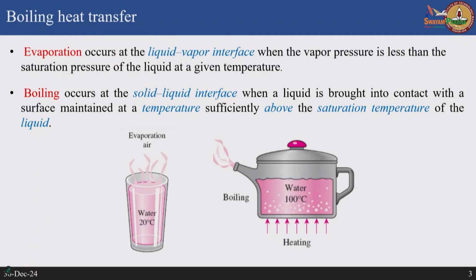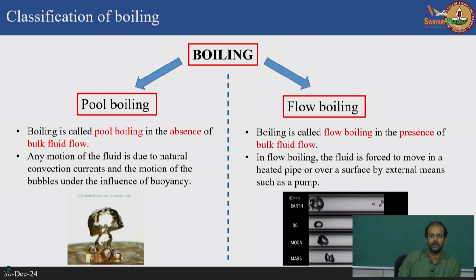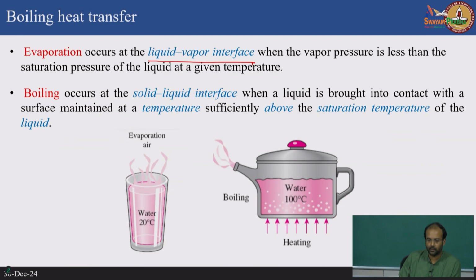Anyway, another important thing when we talk about boiling is you have to understand, technically as a heat transfer person, what is the difference between evaporation and boiling, because we usually interchange evaporation and boiling in day to day life. We try to refer to the same thing, and even heat transfer engineers like me use evaporation and boiling interchangeably, but there is a very subtle difference. Evaporation is something that occurs at the liquid vapor interface. This is clear, but what is the driving potential for this evaporation? It is not temperature difference, but concentration difference.